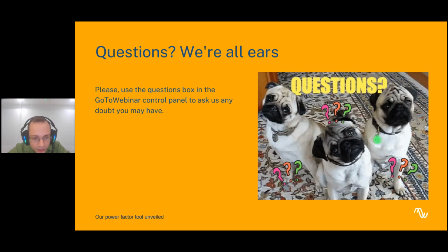Okay, so I'm seeing that in some places there's a requirement of a power factor of 1 at the point of connection at the grid company. This might require reactor compensation at higher voltage. Yeah, for now, we are only providing capacitor banks as the only option for compensation. If there are any other strategies, we will think about them.